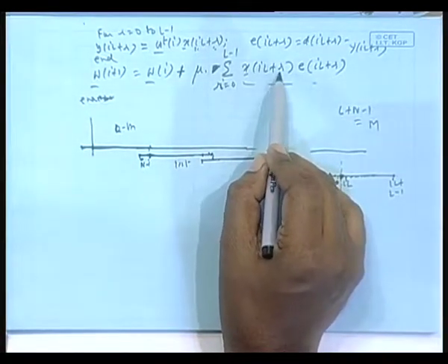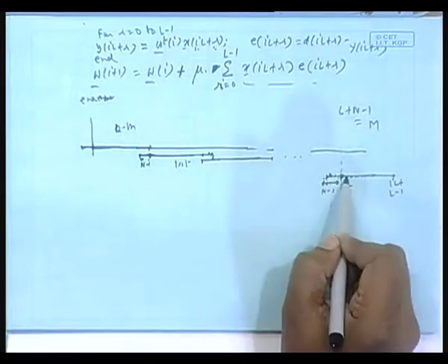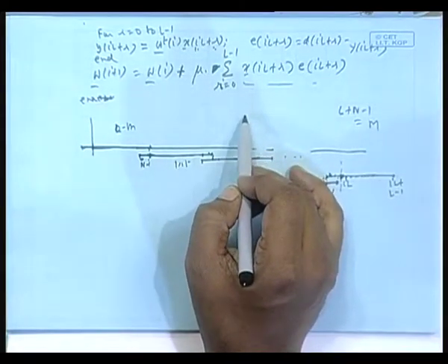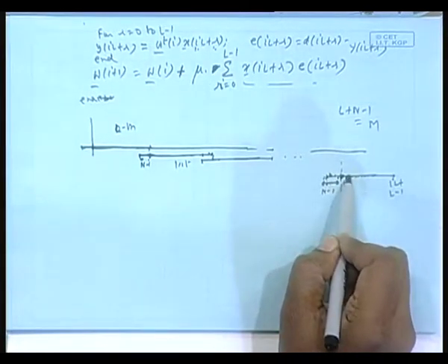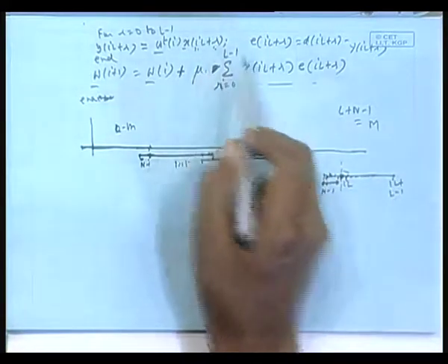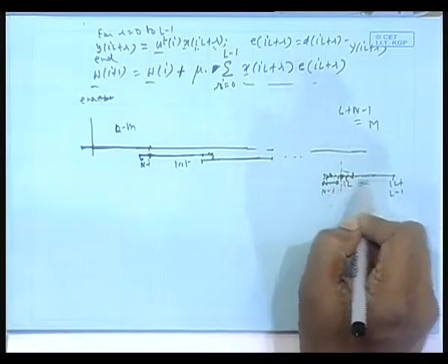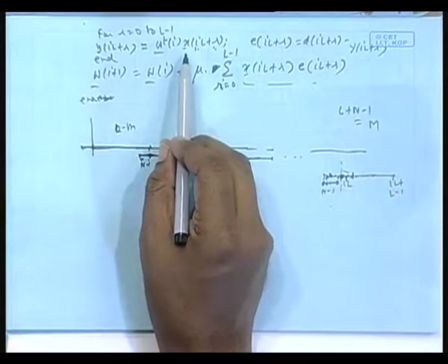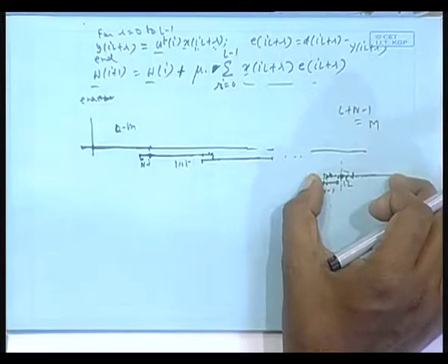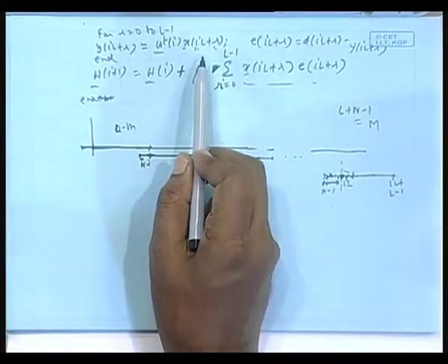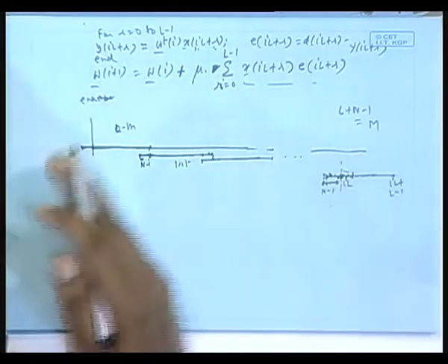Put r equal to 0. I will draw it separately on a page, but just here you see the data structure. IL means the ILth point, and IL minus 1, IL minus 2 up to these, the same points. The data vector at this point will consist of data up to these. Then IL plus 1 means you are going to the next one, so data up to one less from here, and so on and so forth. So, remember in this weight update part, what are the data samples involved? The data samples present in this block. First, how? Because in the XIL vector, I take this entire vector and then this point, and progressively I go to the right.